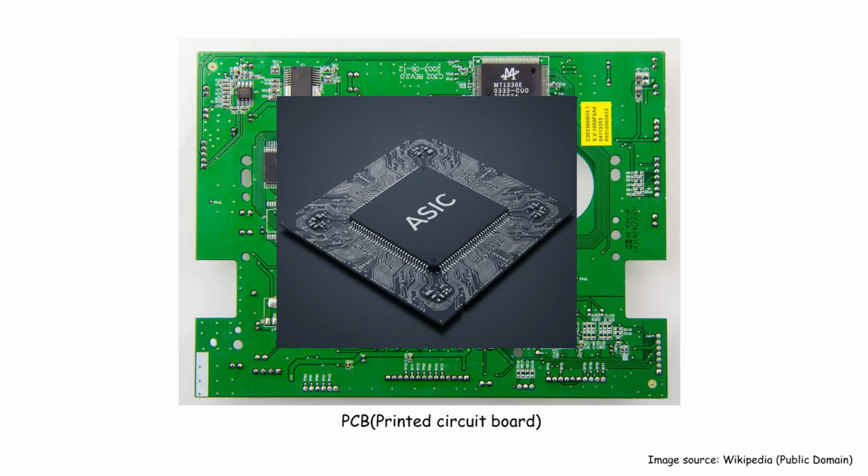So why do we still make ASICs or dedicated PCB products? Because their performance is far superior and they're suitable for high-volume production. By including only the necessary functions and optimizing each data path, ASICs are inherently faster and more efficient. Also, once production volumes hit a certain point, say 100,000 units, ASICs become much more cost-effective than FPGAs. Think about smartphones. They're designed to be compact, power-efficient, and manufactured in massive quantities. That's why chips for smartphones, PCs, and similar products are produced as ASICs rather than built with FPGAs.